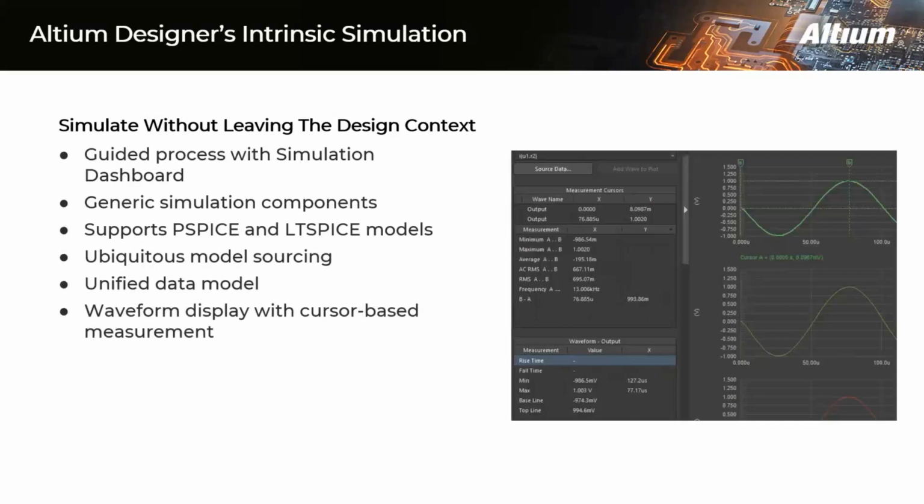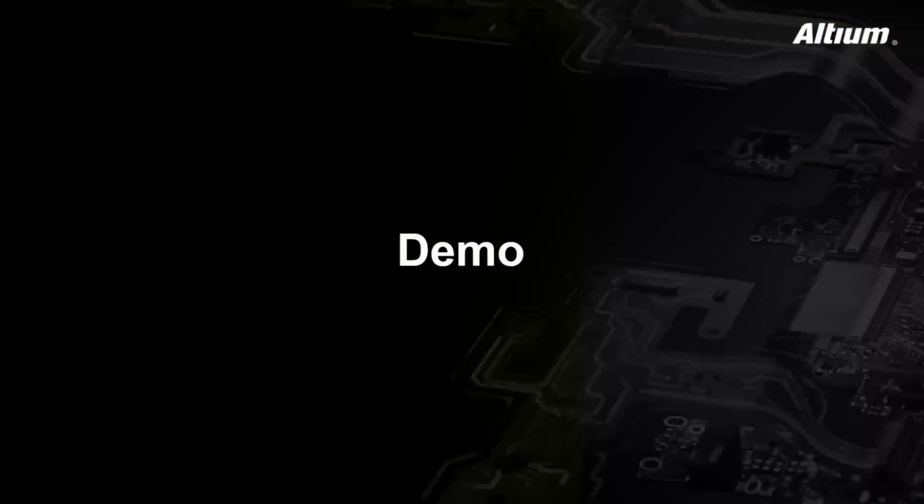The waveform display is treated as a separate tab in the same unified project, just like schematic, PCB, or active BOM editors. You can tile views, probe across schematics, and perform cursor-based measurements of waveform results as shown here.